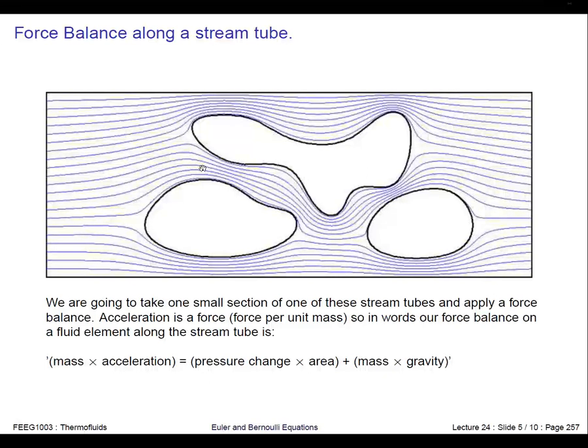Okay, so the pressure gradient, if you like, has a negative sign, and the local pressure goes down. And then when we get to this point, the high speed region, there's lots of inertia here. Then we move into this region, and the flow is slowing down, so its inertial force is reducing, so the pressure gradient changes sign, and the pressure has to go up. Okay, and it keeps doing this. It goes along here, it has to accelerate here, so you have lots of inertia force, but low pressure, and then the flow slows down, the pressure recovers. So pressure changes in a moving fluid, and it responds to its inertia.